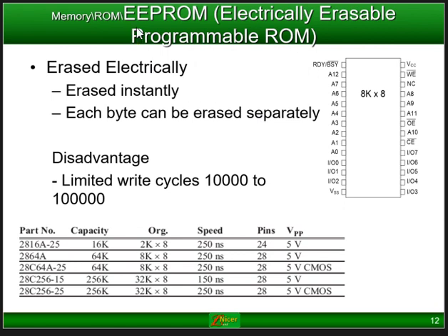The next one, which is not old technology, is electrically erasable programmable read-only memory, or EEPROM. This specific type of memory is still used in the AVR microcontrollers. It's actually embedded, part of the memory inside the AVR microcontrollers. It's part of PIC microcontrollers, but you also get EEPROM memory devices that are a chip on its own, which you can also use to program. And once you've programmed it, you can program data on there, or you can actually program instructions on there.